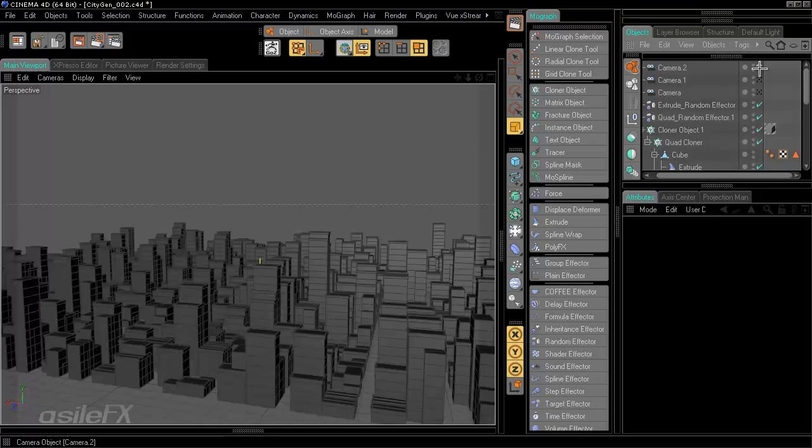a little variation. Now if you do want to have some individual scale changes for the height of that top portion, you can add an effector just to that specific extrusion step. Now what I was talking about before with using a cube and just changing its overall scale with not setting up steps, which is entirely possible, and with the pivot point on the bottom of the object, it will always scale upwards. You won't have anything going down below the ground plane.